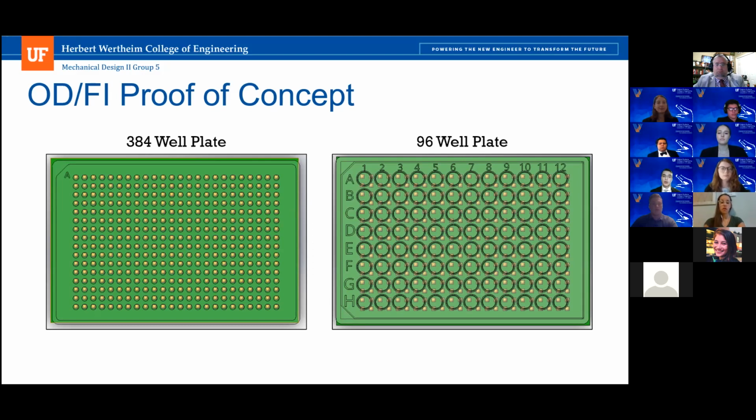And so we can just light up one at a time, or in the case of the smaller number well sizes, we can illuminate a few at a time to ensure that there's no cross-contamination of measurement due to exterior lighting. For the smaller number sizes, such as a 24 well plate, it is guaranteed that there will be at least one LED underneath those wells, as the distance between two LEDs is approximately 6 millimeters, and the well diameter of a 24 well plate is about 14 millimeters.